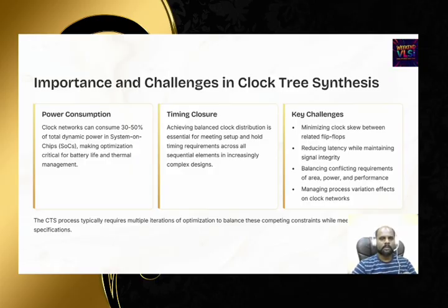And the other one is power. The clock network, both your flops as well as the entire buffer tree you have synthesized, toggles a lot, because the clock goes 0 1 0 1 0 1. So these circuits also toggle a lot, and there will be switching power and short circuit power.